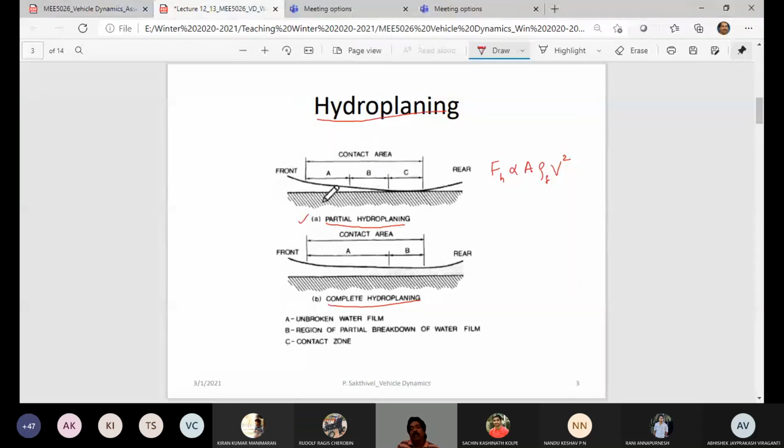Suddenly you see the road filled with a fluid surface, and you may have such a scenario called hydroplaning. And that is going to happen whenever you are braking on the surface. Whenever you see there is a sudden change in the road surface, you see there is a fluid on the road surface, you tend to apply the brake. When you tend to apply the brake, what would happen? The phenomenon is called the hydroplaning phenomenon. So that is all because of the hydrodynamic lift force.